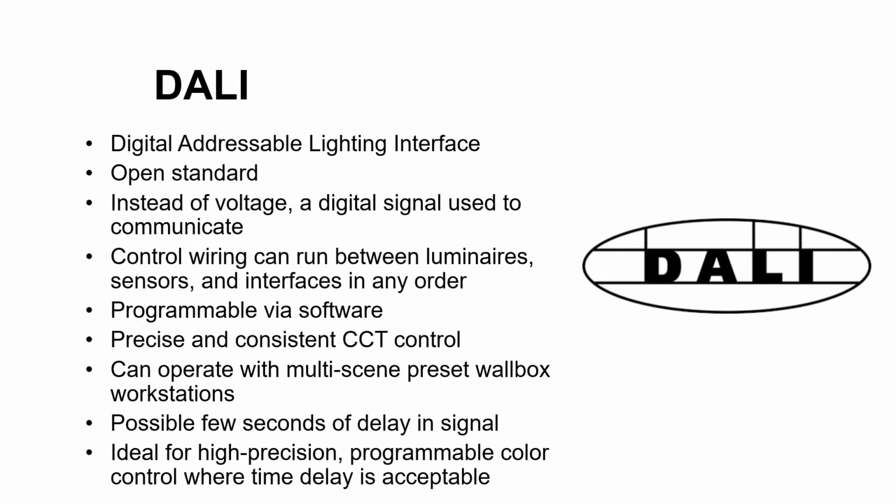DALI stands for the Digital Addressable Lighting Interface. Also originally designed to control fluorescent dimming ballast, the controller sends a signal to the LED driver that ranges between 0 and 255 in integers, which an algorithm then translates into light output.